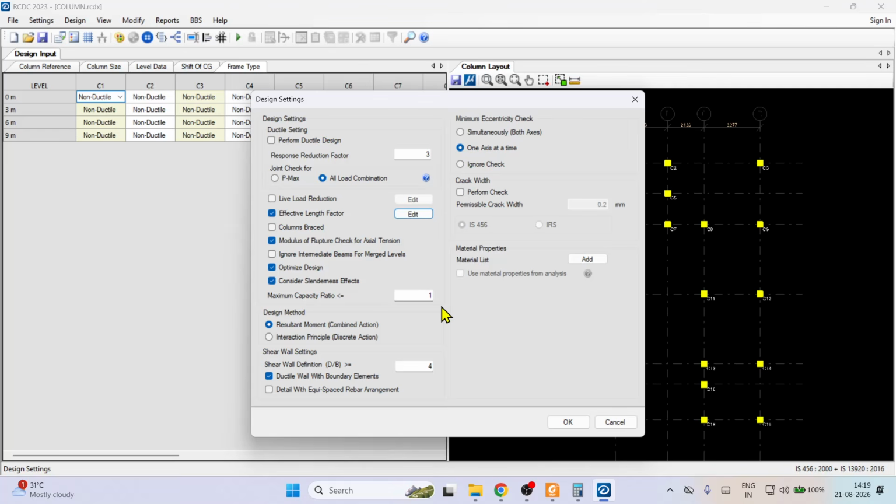Why are we interested in designing a weak beam and a strong column? Because if one beam fails, our structure will not fail, but if one column fails, our complete structure fails. So we can say column failure is global failure and beam failure is local failure. Local failure we can manage, but with global failure the complete structure will fail.